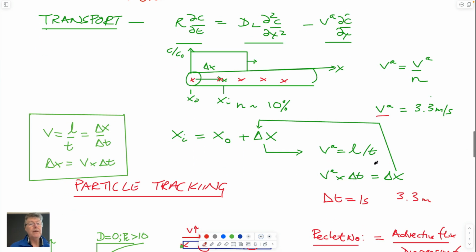So if we wanted to solve the transport equation, we could use this, but we could use a slightly different method by realizing that we want to represent this plug flow behavior. Simplest for us to think about it. And we know that as we go down gradient, the distance the plume will travel as we go in x, and c over c0 would be a length, which is equal to, velocity is equal to length over time, so this would be velocity times time, right? So maybe we can mimic that somehow just by using finite differences again.